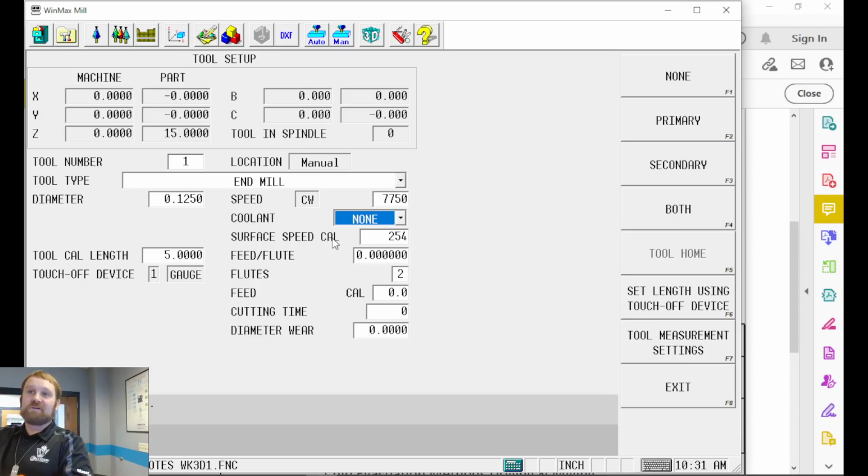Everybody, there's reasons that there's entry-level RPM spindles and there's high-speed machines. And it's all about what you're doing. If you're cutting a lot of hard, aggressive metals, you need a high horsepower, probably not a lot of RPM spindle. Okay? If you're cutting a lot of mold and die stuff where you're doing a lot of high-speed machining and finish work, you need a high RPM spindle so you can move across that part and get stuff done. Checks and balances, right? We've got to know where it applies.